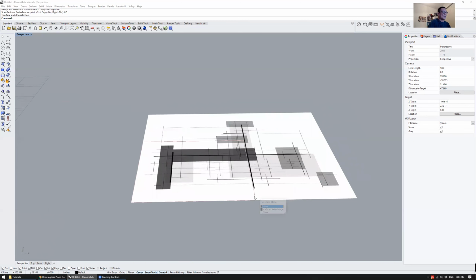So instead of trying to guess using numbers, I can run the scale command again. And you'll see that spacebar just repeats the previous command. So if you're repeating the same command over and over, then just spacebar, it'll bring you back to the same command. Escape basically escapes out of any sort of command or selection, okay? Anyways, let's run the scale command again.